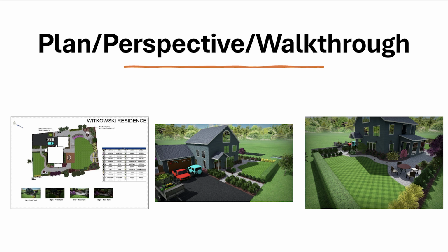A tool that is specific to Realtime Landscape Architect is the Perspective view. The functions are similar between Perspective and Plan View, but some functions can be better in different tabs. For example, the Perspective view allows us to get a better size and scale representation of plants in the landscape to determine how much space is left, whereas in Plan View, inserting a single plant or plant row is done easier in that view. Also in Perspective mode, we are able to see a 3D perspective of our house, and it also allows us to add in different features like site amenities, lighting around the house and landscape beds, and also the windows and doors.